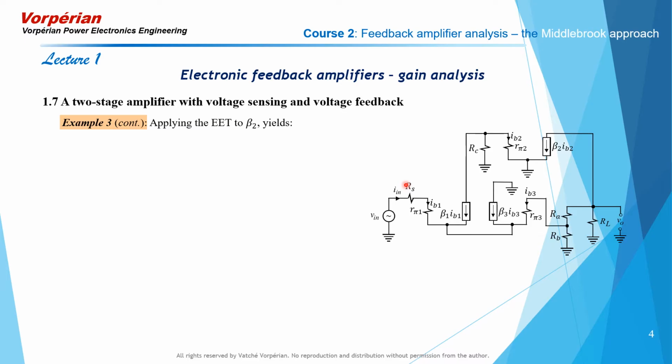All you have to do is go into the forward amplifying path and recognize that if beta 2 were to become infinite, then the voltage gain from this node to that node becomes infinite. If, on the other hand, beta 1 were to go to infinity, then the voltage gain from this node to that node will not become infinite, only because the emitter here is connected to ground through some effective resistance. We don't need to know what it is, but we just know that there is some resistance between the emitter and ground. As for this stage here, it doesn't contribute anything by way of gain from the input signal to the output. So it is beta 2 that we designate as the gain element and apply the feedback formula given by the extra element theorem for beta 2.